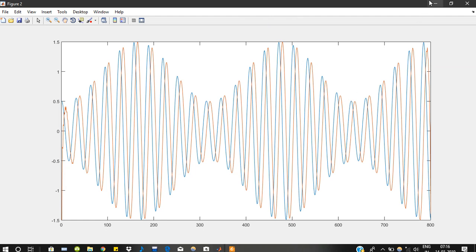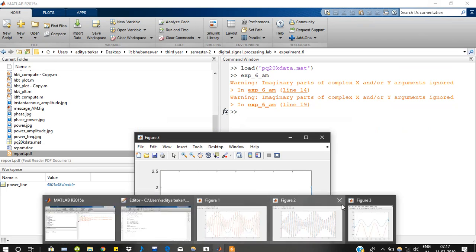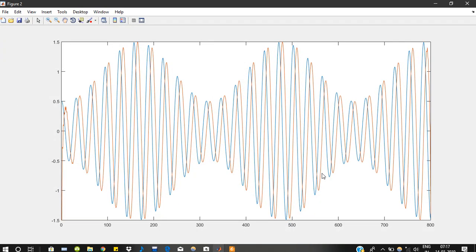Now for the instantaneous amplitude: once a quadrature phase shifted signal is achieved, it is taken this way. To achieve this quadrature phase shifted signal, after modifying the DFT sequence you need to perform an IDFT, which gives you a time based sequence.